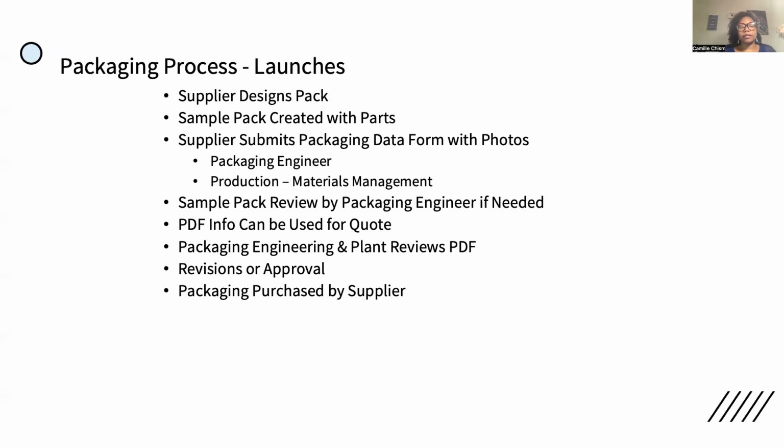Also, they need to have sample packs that they need to create, and you need to be able to have a fit check. And I would say you, as a packaging engineer, you want to have a physical sample of the pack. It could be a prototype pack, it could be a dummy pack. And for the fit check, you also want a part. It doesn't have to be a working part. It doesn't have to be a complete part. You want something that fits. So it could be a 3D printed part. You want to make sure that this part fits into the packaging. Okay, that's the first step.